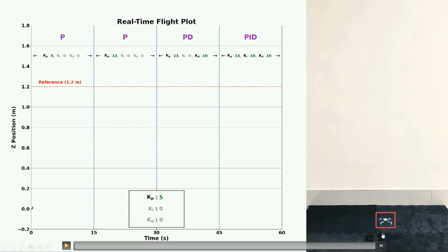Again, theoretically, if you remember, if I am just controlling the altitude, the transfer function is 1 by s square with acceleration as input, and we know that a PD controller should take care of this. But you will see that this will not be the case practically, because when the drone is flying, it is moving in the xy direction also.